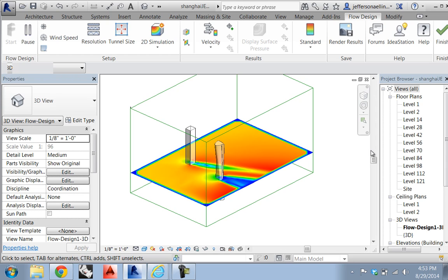So depending on which direction the airflow is coming from, you can just slide this around, and it'll change the direction that the airflow is moving through the solution space. Right? Pretty straightforward. And you can also see quickly that, just by changing it, we get a different wake profile behind this geometry, depending on how it's reacting to the geometry at that space, which is pretty quick, pretty easy to see.